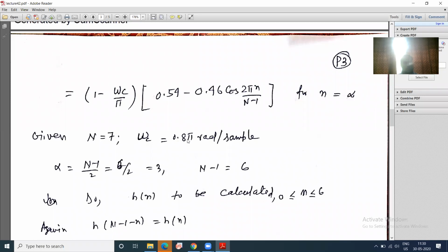But phase response is not required because the different kinds of filter, low pass, high pass, band pass or band stop filter, can have the same phase characteristics, because this is dependent on the kind of symmetry condition that you choose, and also the center of symmetry. Agreed? So phase is not an important parameter for plotting or understanding the signal. However, phase linearization is required to remove or eliminate the phase distortion. All right.